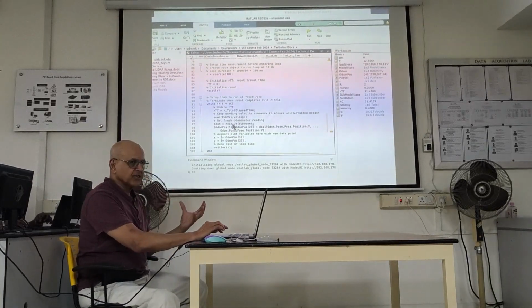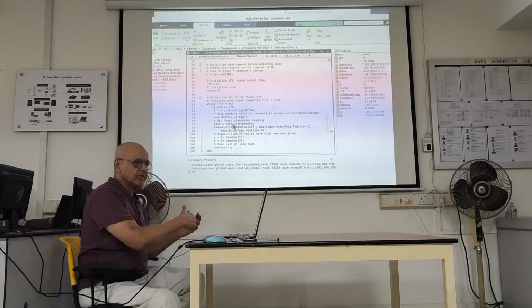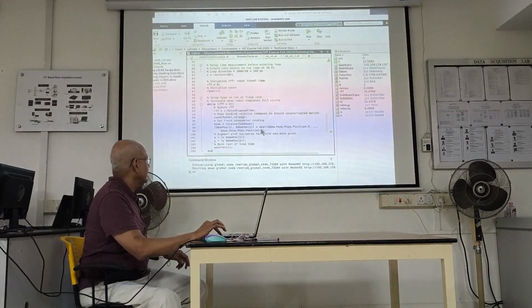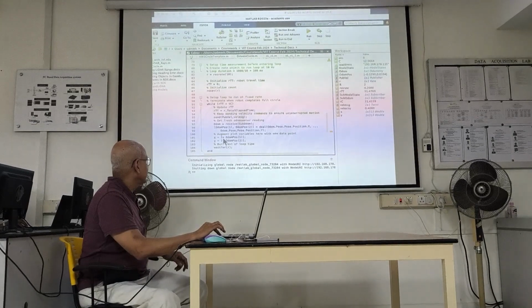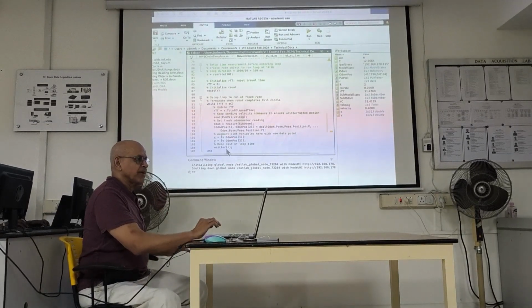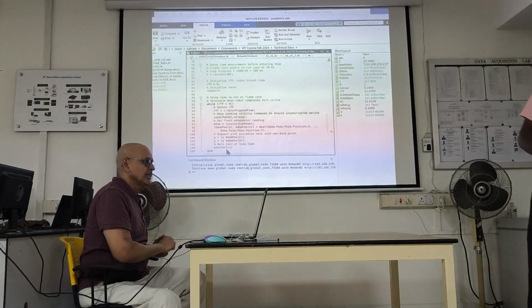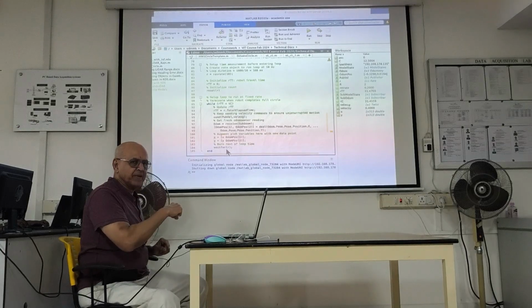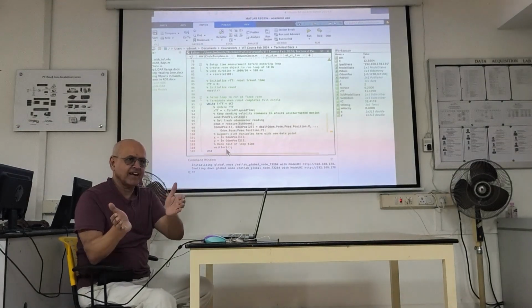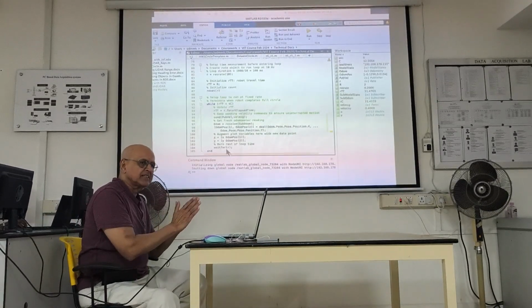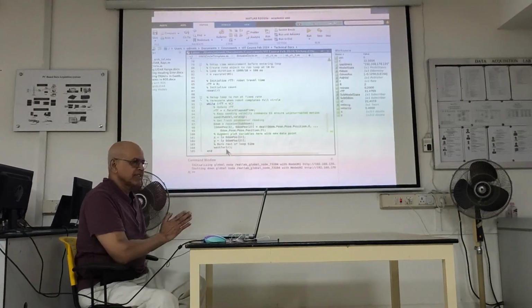So now you have to get a fresh odometry reading to put it in the plot variable. Because you want to plot the circle. So I receive and do the same thing again. And I augment X and Y. And then I burn the rest of the loop time. So if you had other tasks to do, then this time will be handed over to other parts of the MATLAB program. But here it's just going to wait till 100 milliseconds are up.